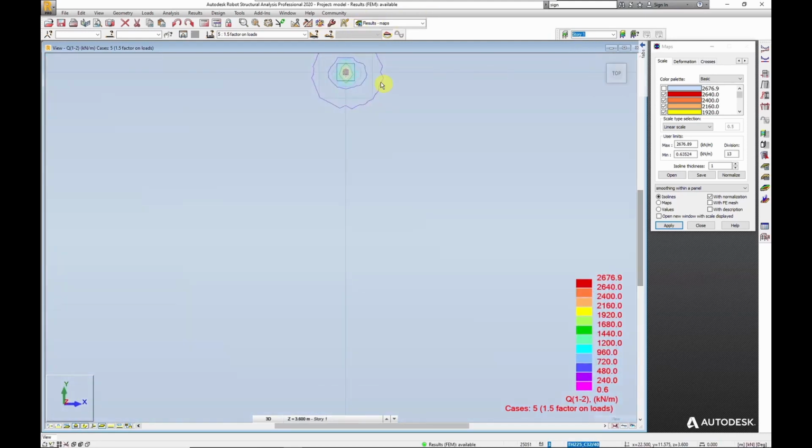If I go back to the top view, that bigger square is the shear perimeter. Again, just for convenience, it's square, the old BS 8110 shear perimeter. Obviously, if you were using EC2 or some other code, you might have curved corners to this. But again, it's really the principle I'm discussing here.